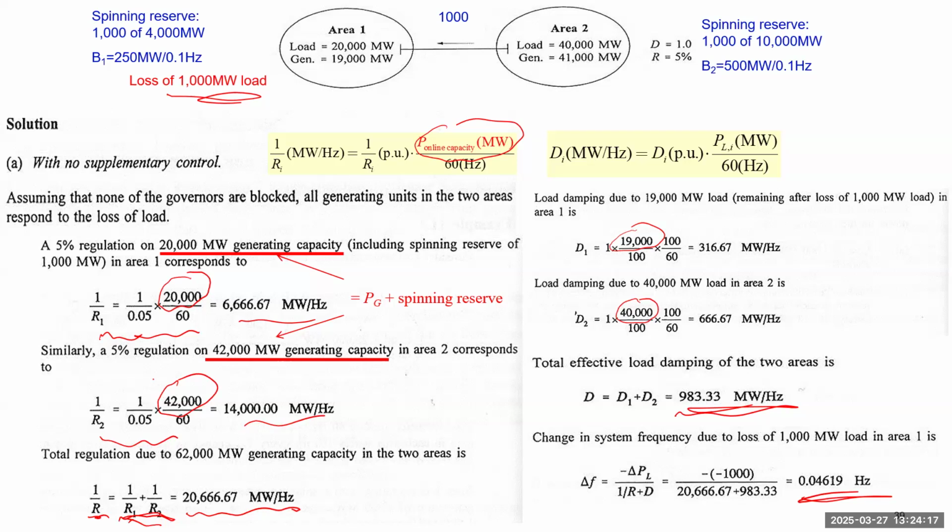We just roughly know this information, but which is enough for our calculation. But notice the total generation for the entire area is 19,000, which means only a small percentage of the generation carries spinning reserve, or they are actually connected to AGC, not all of the units.